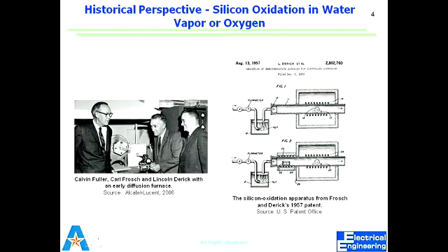Now, think about it. If I have silicon which is electrically active, and of course after doping, and I put silicon dioxide on it, how do we approach silicon through silicon dioxide? Etch. What is etch? Etch is you take off something chemically, so removal of certain material. So I have a whole surface covered with silicon dioxide, and I have silicon beneath. There will be silicon dioxide from both sides. So I have to remove silicon dioxide from precisely known places, so I can approach the silicon below that.